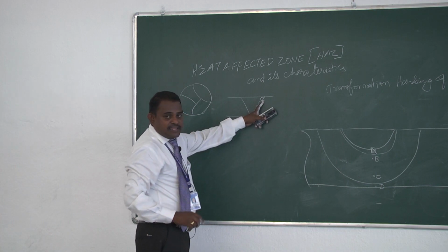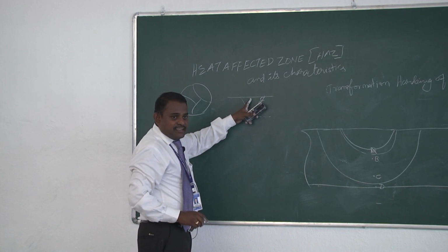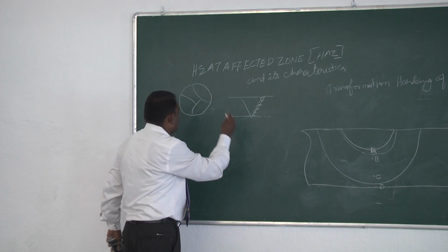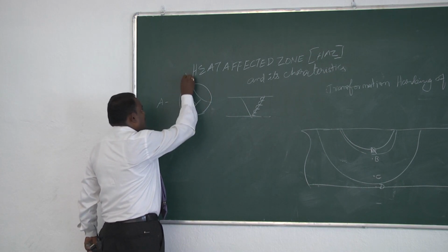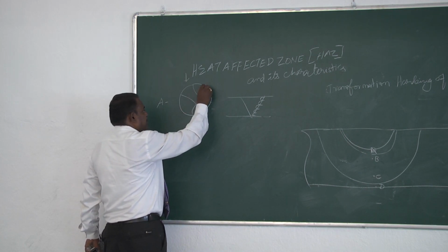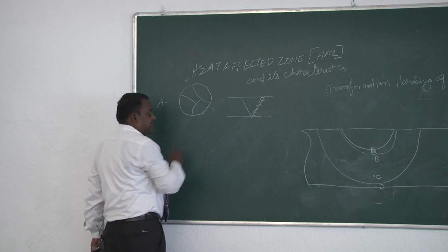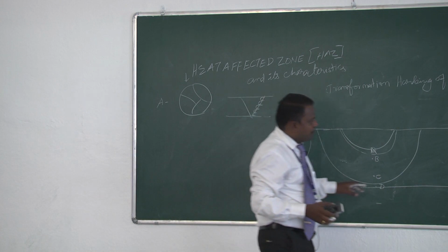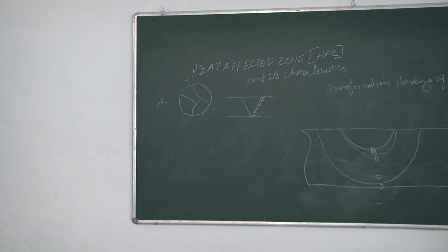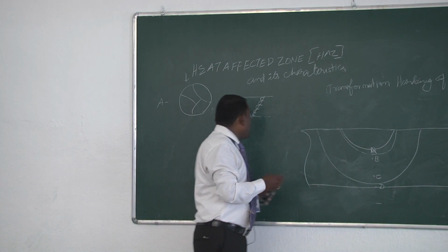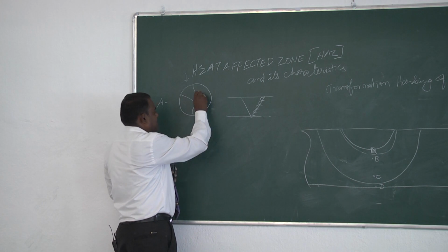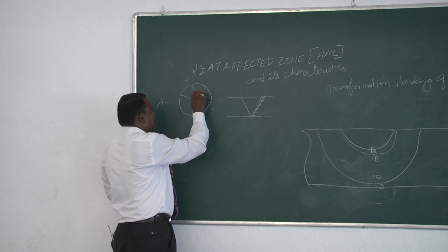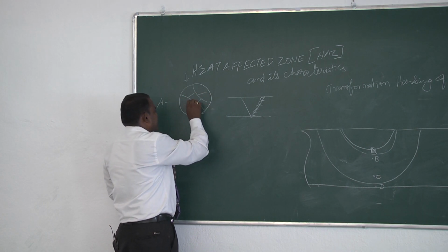This partial melting region will act as a nucleation site for the growth. It will definitely undergo a high temperature, so it will be in the liquid state, and atoms are free to move. Then it combines to form delta iron with liquid, then it comes down to gamma, and then you will have the final microstructure like this. That is the reason you will have a very fine grain structure.